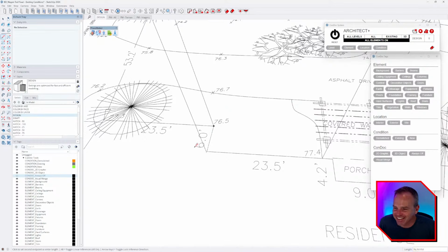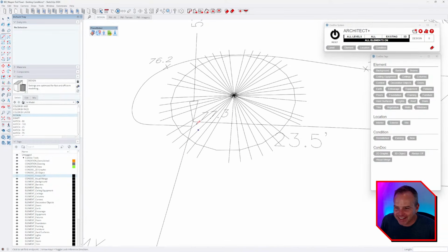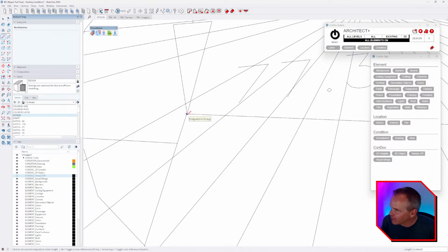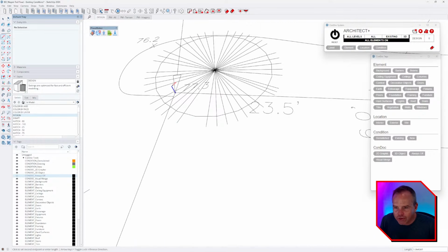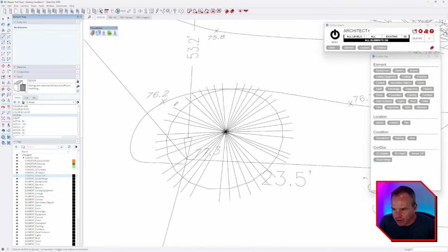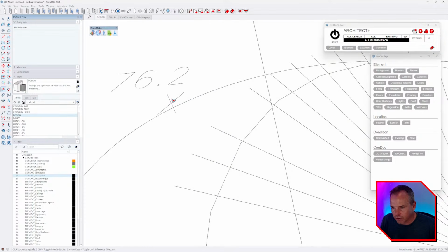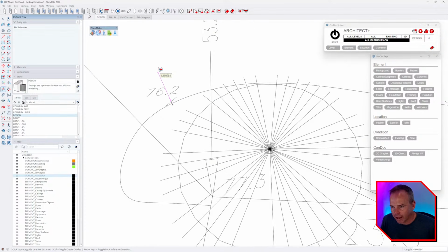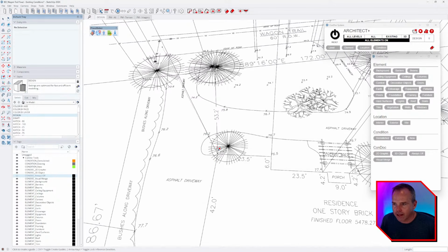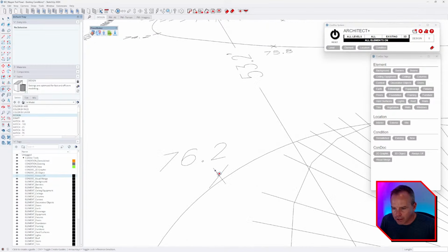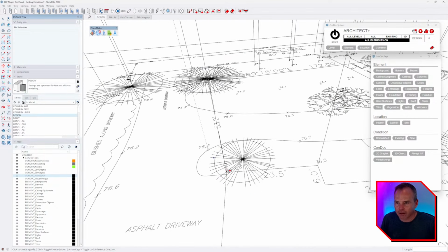and Justin, yes, those guide points, right? So that was that gentleman's, that was why he was using the Fredo tools or whatever, because it draws those guide points. And I suppose I could draw using my tape measure tool, tap Control and type 76.2, and then you get your guide straight up at 76.2.